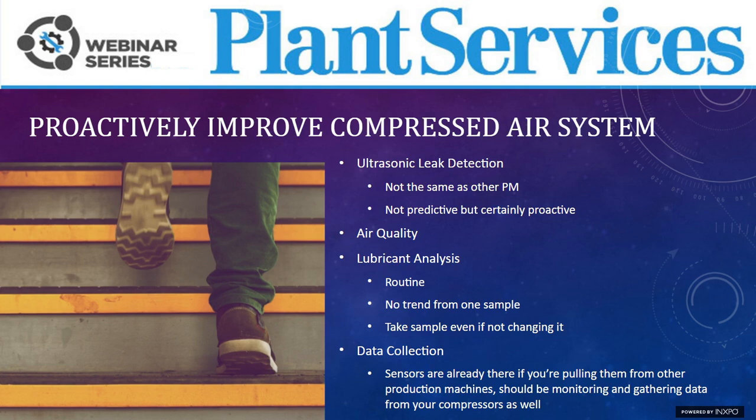Compressed air systems evolve over time, and the best way to shepherd your system to a long lifetime is to monitor it. Timothy highlighted onboard data trends, but there are a few that should be considered either in addition to or in conjunction with this data collection. Specifically, ultrasonic leak detection, air quality, and lubricant analysis. Most industrial equipment already has sensors installed that can be used to bus to other networks, but these are pieces that are different.